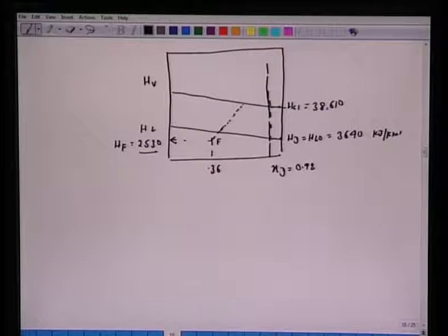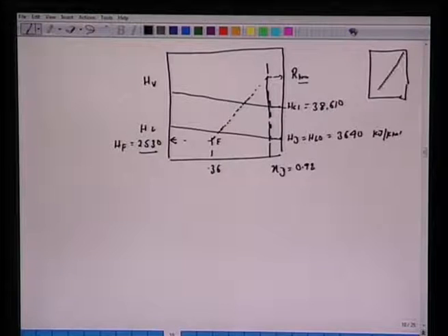If you take this tie line and extend, this will give us R. Again, it's very important that we understand that we require the TXY diagram to obtain this R. So we have the TXY diagram here, or we have this Y versus X diagram. Generally the TXY diagram is given to us.